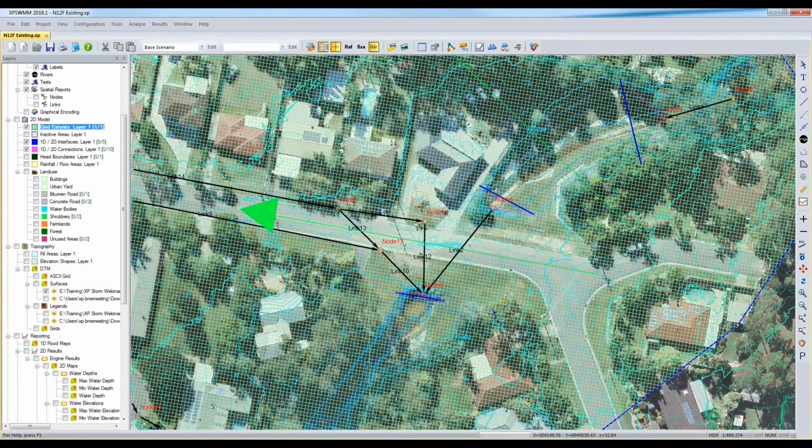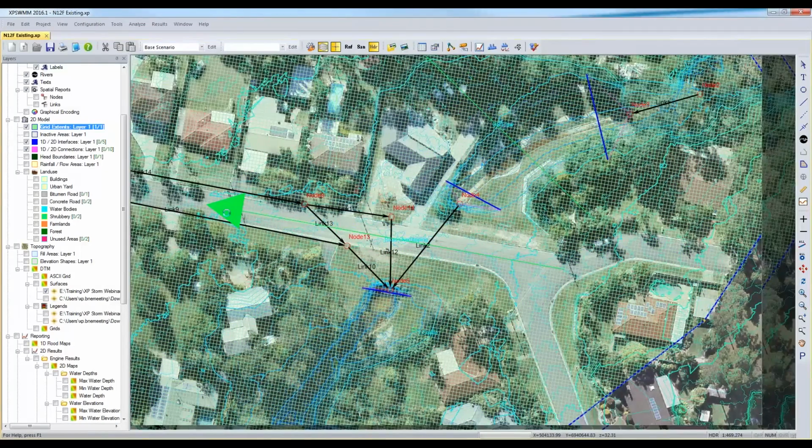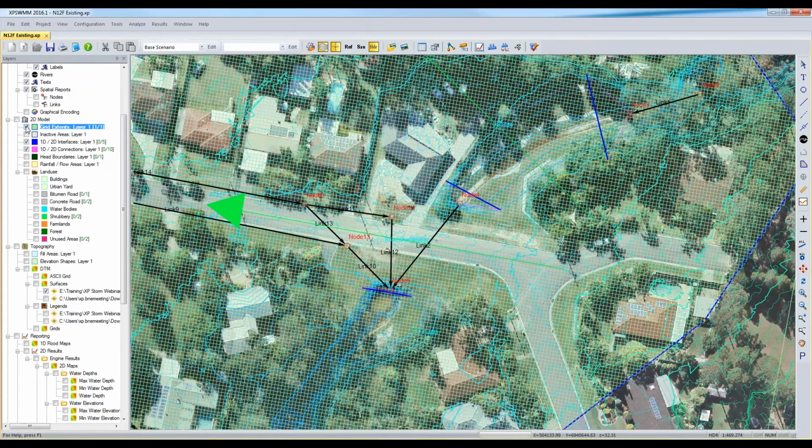When you've got a big network, it can be hard. It helps when you've got 90-degree roads, but with a lot of modern road networks, the roads are all over the place. So in that case, you just want to make the grid as small as practical, and line up as best as possible where you've got sensitive areas like sags. The only other thing is we haven't done this yet, but I believe you can do multiple grids. Yeah, there's a multiple domain option where you could set up as many grids as you like and link them together, and of different sizes too. I believe that's a separate module that Logan isn't using, so you don't need to use it. But it's a handy little tool. It'd be useful for areas where you have lots of roads coming at different angles, if you find the need. So I'll turn that off now.